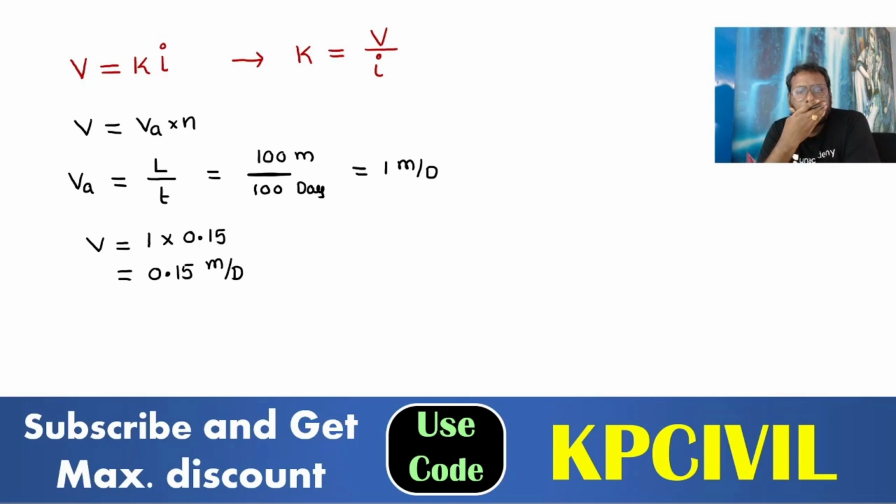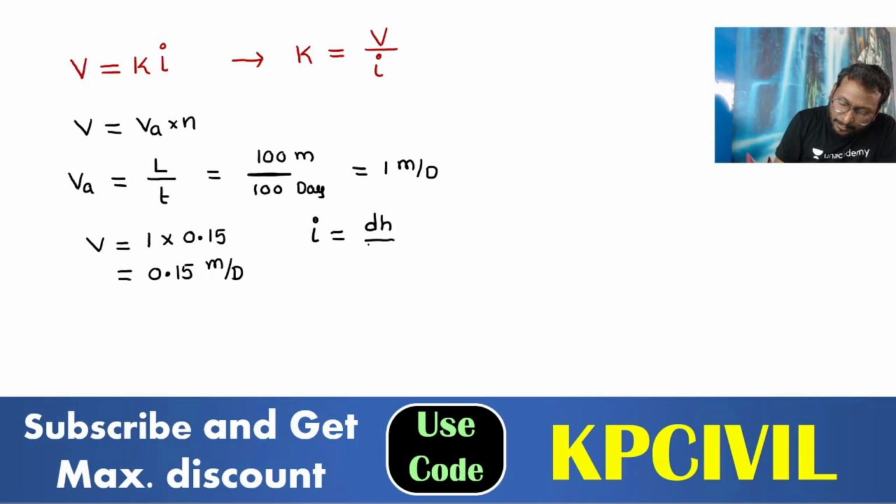Any difficulty here? Given is the actual velocity, distance by time, 1 meter per day. You need the apparent velocity, V is VA into N, 1 into 0.15, 0.15 meter per day. Then, what is I? I is equal to DH by L, head by distance. Head is 3 meter, distance is 100 meter. So, we can take it 0.03.